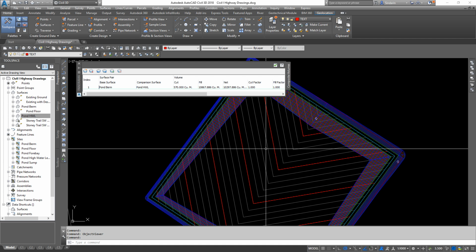It'll turn everything into 3D polylines, but you just put it back on the same site, re-add it back to the surface, and it accomplishes the same option. Whether it's a grading object feature line or a regular old feature line, the regular old feature line is going to be more stable than a grading object. Now, again, I've lost drawings due to grading objects, and it's purely workflow related when that happens.